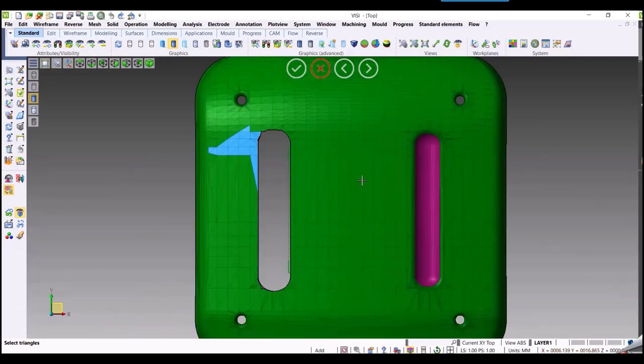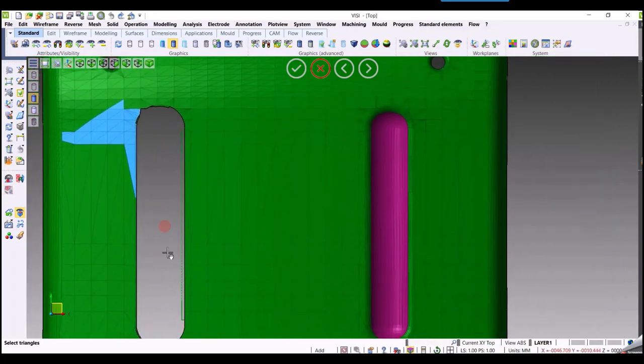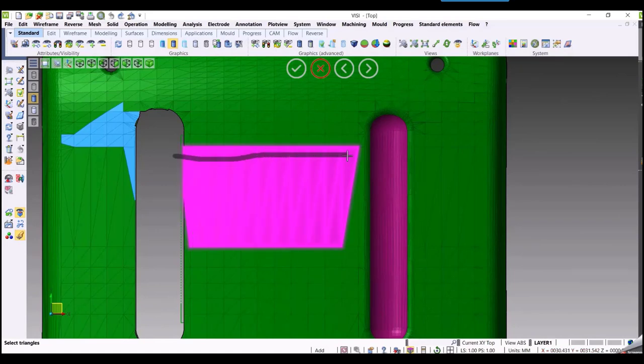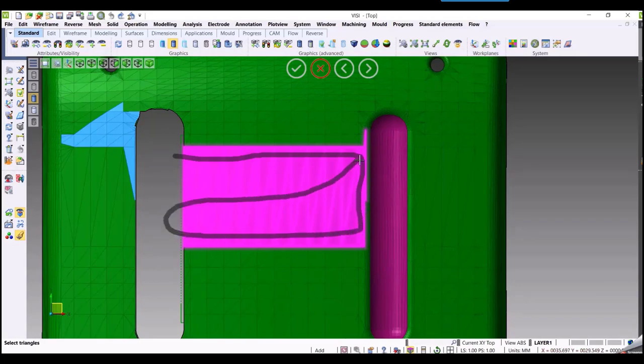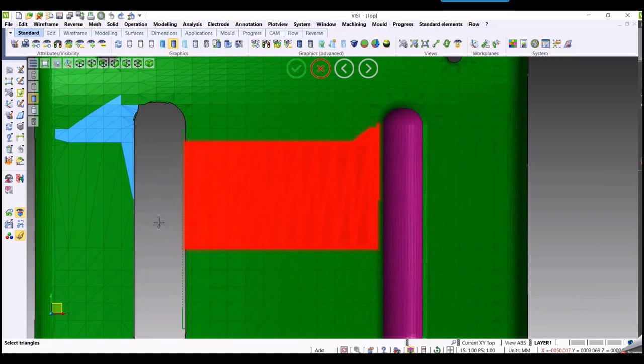And then lastly, we have the brush stroke selection. Just like what was shown before, if I hold the Alt and wheel mouse button, I can pick these triangles specifically with the brush stroke. So you can see how it's painting your selection on your dialog, and it's only picking those triangles. So as you can see, we now have the ability to select those with the brush stroke as well and change brush stroke size.